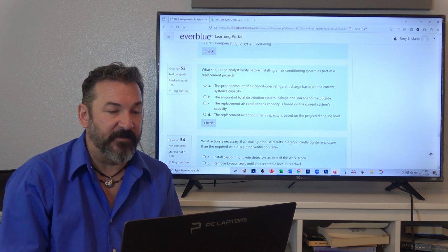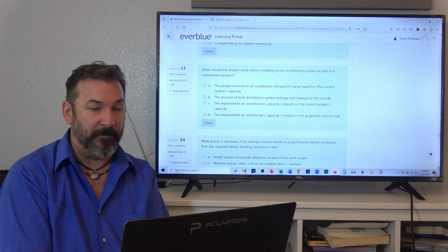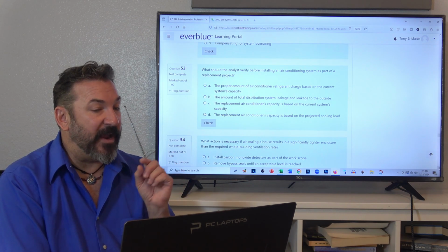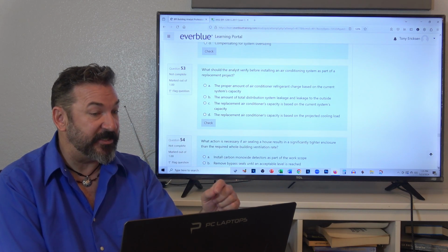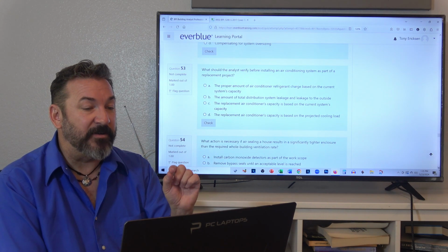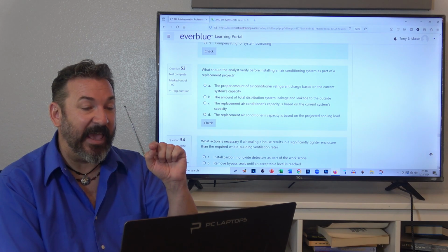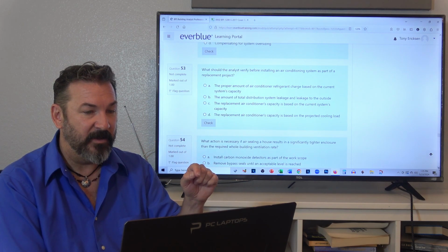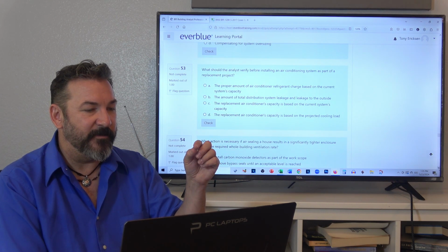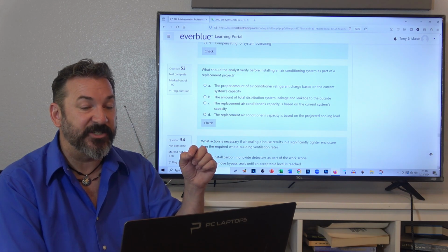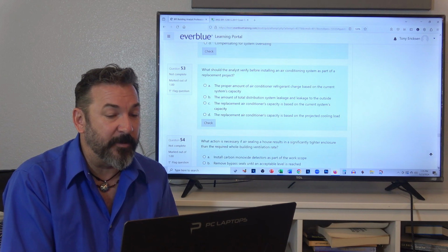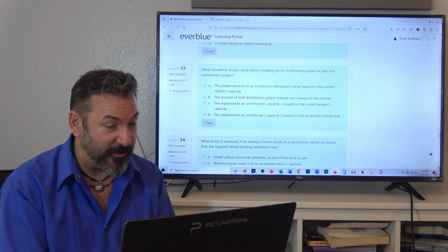Question 53: what should the analyst verify before installing an air conditioning system as part of a replacement project? The proper amount of air conditioning refrigerant charge is based on the current system? No. The amount of total distribution leakage to the outside? We're replacing the system. The replacement air conditioner's capacity is based on the current system capacity? No. Replacement air conditioner capacity is based on the projected cooling load. Yes. There you go.